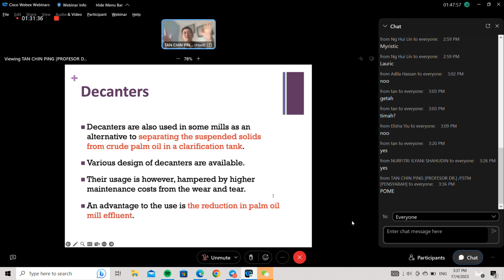It is many discs that join together. The disc is a stainless steel disc. So when you have solids, especially sand, centrifuged at very high speed, the sand will touch the disc and the disc will get dented because the speed is very high. It's like a bullet. The disc is a thin layer of stainless steel, so a bullet may pass through it. Although you have steel, a bullet can still pass through. So you can imagine many bullets passing through many times. Therefore, the disc will get dented, and dented.